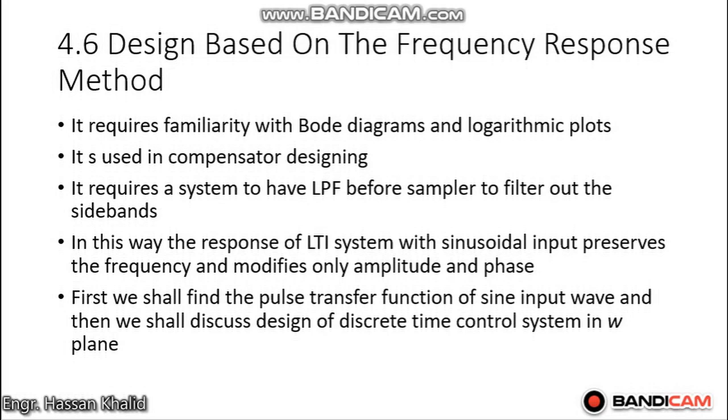design based upon the frequency response will be very useful while you are designing the compensator. Either you want to compensate your output with respect to the leading mechanism or the lagging effects, you must have deep knowledge regarding the frequency responses. Also, you must place a low pass filter before the sampler so that you can filter out your selected sidebands, which will be based upon the low pass filter, and they must correspond to the low frequencies.